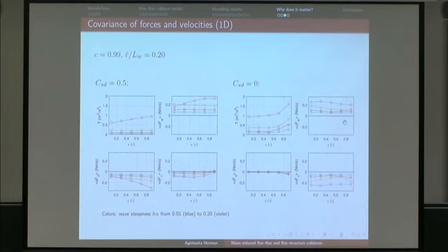So from this point of view, it is interesting to look at the modeling results in terms of how high the granular temperature is and what is the covariance between the fluctuating velocity and forces acting on the ice floe. So we may take separately the wave-induced force, the drag force, and the collisional part of the force. And when we look at the granular temperature, it's not very surprising that it is comparable to the squared velocity associated with the wave motion, of course. So it's the same order of magnitude.